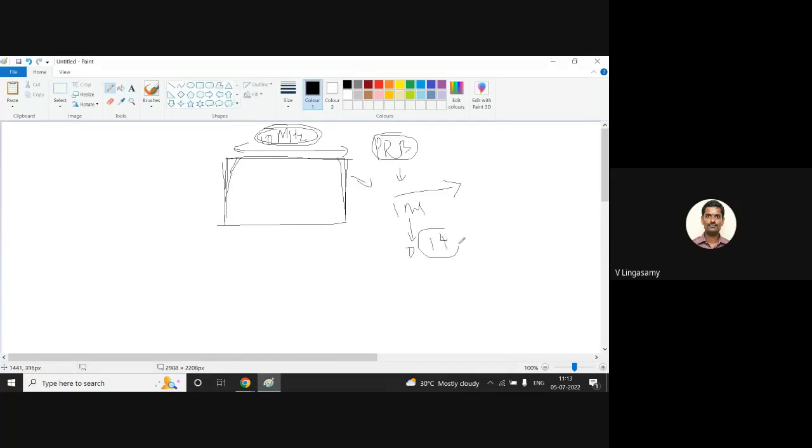So 14 symbols is the fundamental chunk of data. In 14 symbols I can send 2 bits, 6 bits, 10 bits, depending upon the modulation scheme. How is the modulation scheme helping? If I am using QPSK, I can map the symbols, and each symbol will have 2 bits of data. If I am using 64 QAM, I can code 6 bits for each symbol. So how much am I getting? A 3 times enhancement in the throughput.